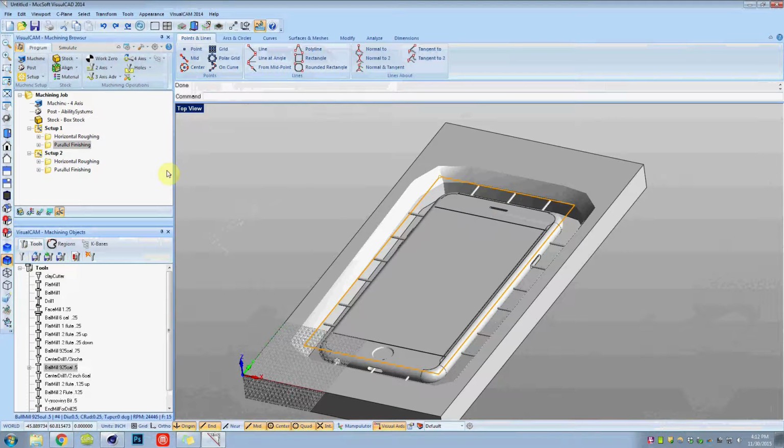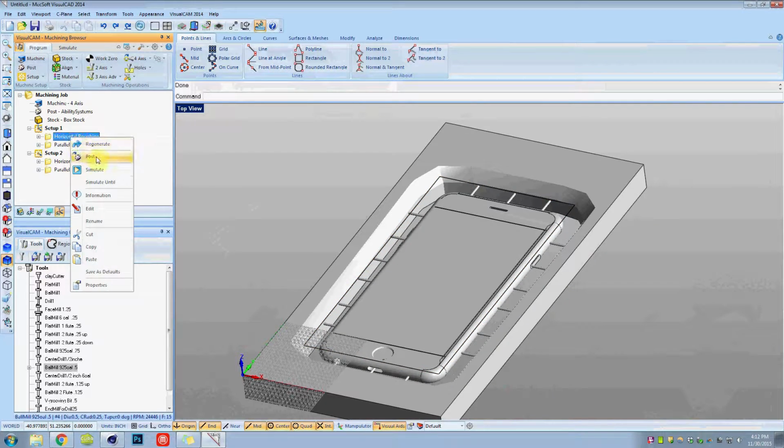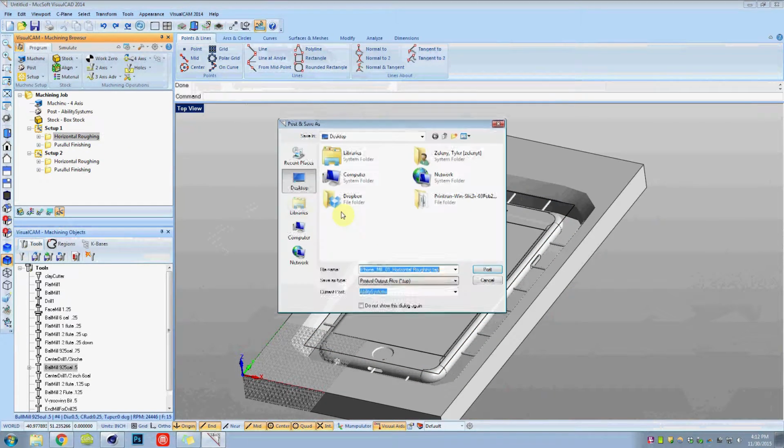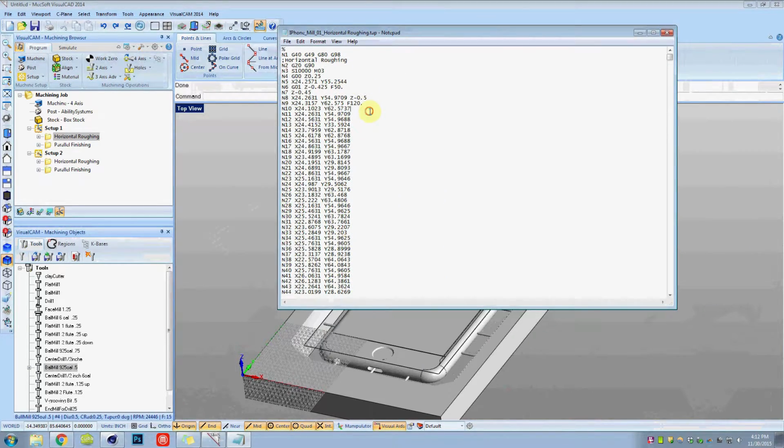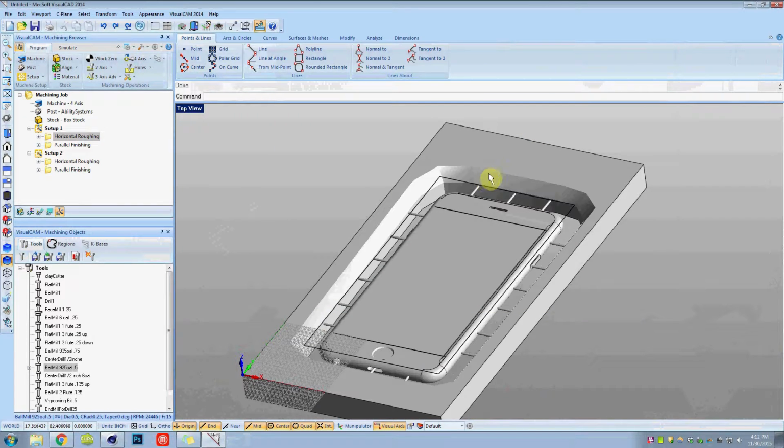And that's it. Then you take the tap file, which you'll see post, and then name it. This file, this is the G code, straight up G code. Save that to a flash drive, take it down to the mill, and run it through EasyRouter's Mach 3 program.